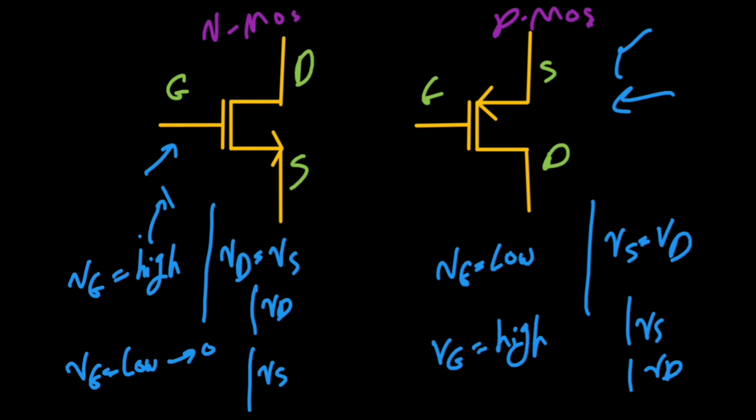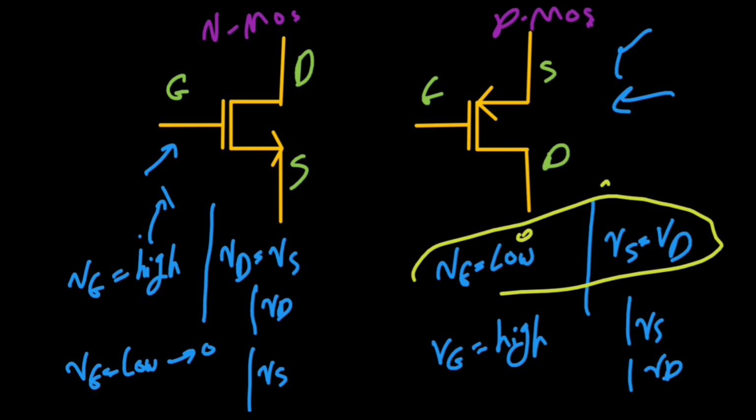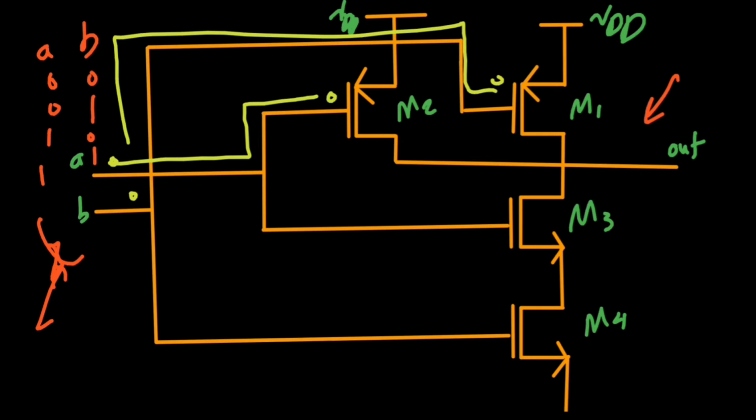In here, we saw if we apply 0 to the PMOS, it would be on, acting as a short circuit. Therefore, this M2 would connect the high, this one to this one, right? It would just be on. Therefore, the VDD would come here. We would have a 1. High voltage is VDD, that we are calling a 1, right?